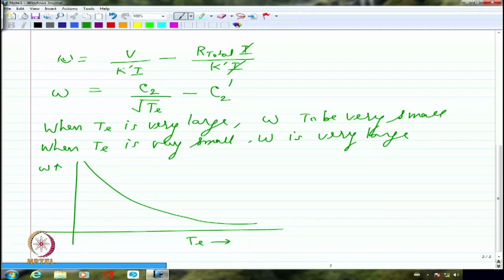Right? So if I try to start a series motor on a very, very light load, the current drawn is going to be really, really small, because the current drawn depends heavily upon the kind of load you have.